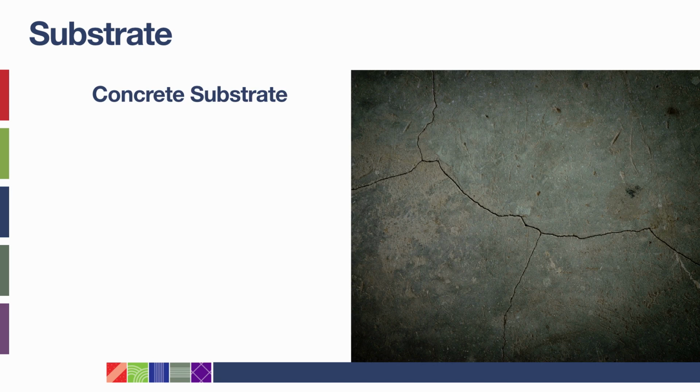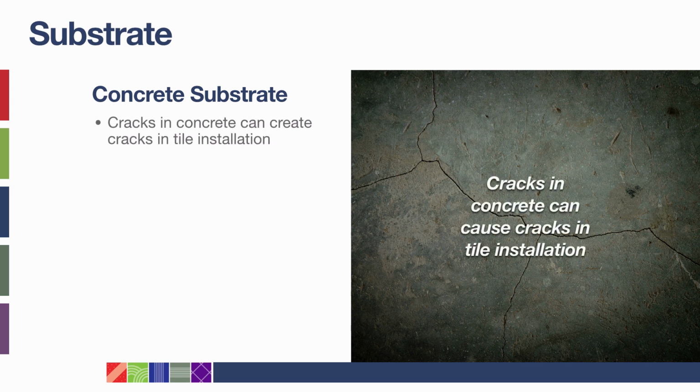Concrete is a very common substrate, but does require that proper precautions are taken. Concrete often shifts, shrinks, and cracks, and that can affect materials installed over it. When tile is bonded to concrete, cracks occurring in the concrete can in turn cause cracks in the tile installation. However, the following statistics should help to ease concerns about installing tile over concrete, or at least help you take